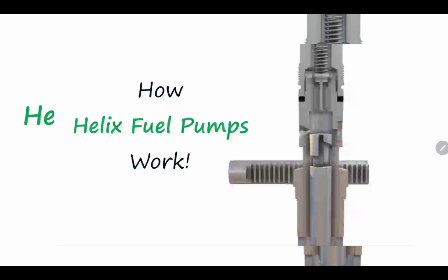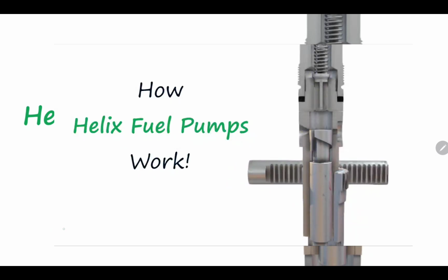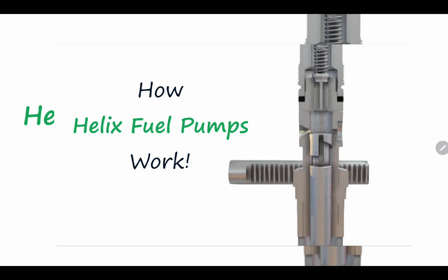Okay, it will be hard to mark it here, so we'll have to watch it and keep a close look. You see, when you rotated the plunger, the return amount of fuel got reduced and the injected amount of fuel increased. Okay? Because the rotation of the plunger delayed the opening of the return port.